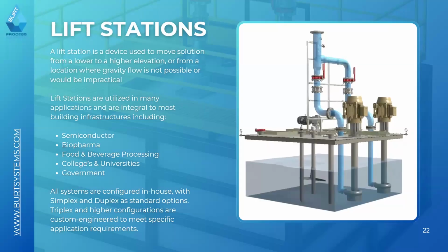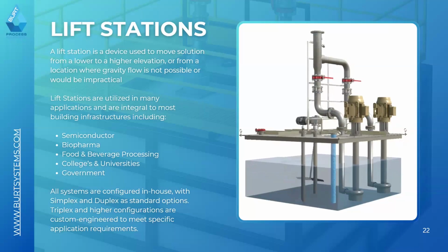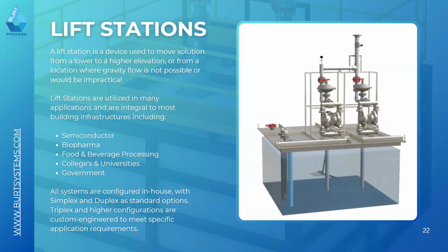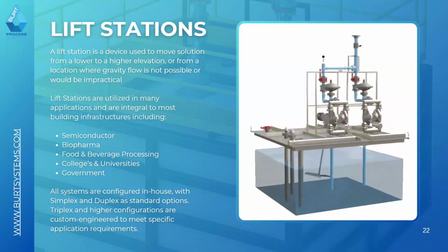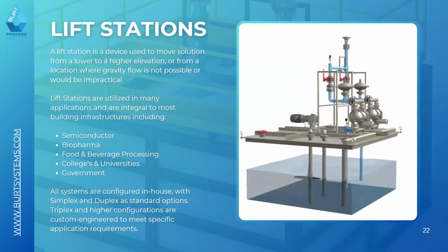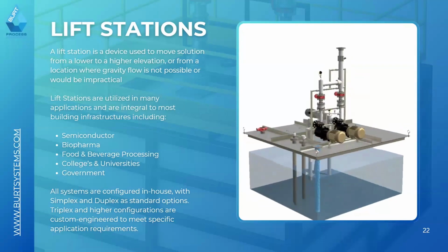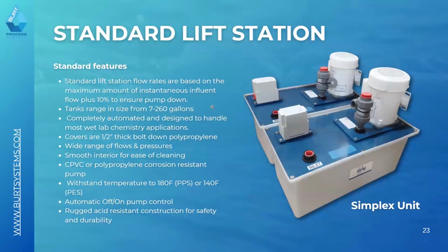Obviously, there are different types of pump technology, from verticals to air operated, for example, if you have explosion proof areas, or even things such as self-primers. If you want to look at pumps that need to be located above, where you have a very high suction lift, or if you don't want the pump in the waste stream, if you're dealing with a very strong waste stream, for example, that can be utilized. Operator safety can become a primary concern at that point.